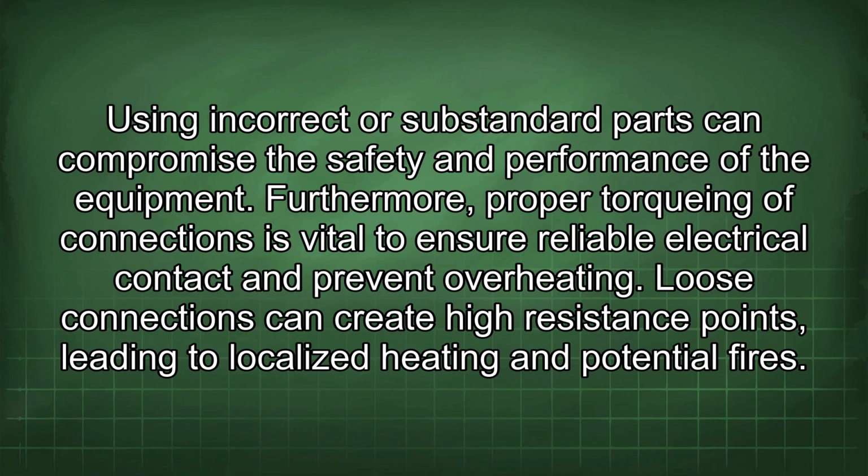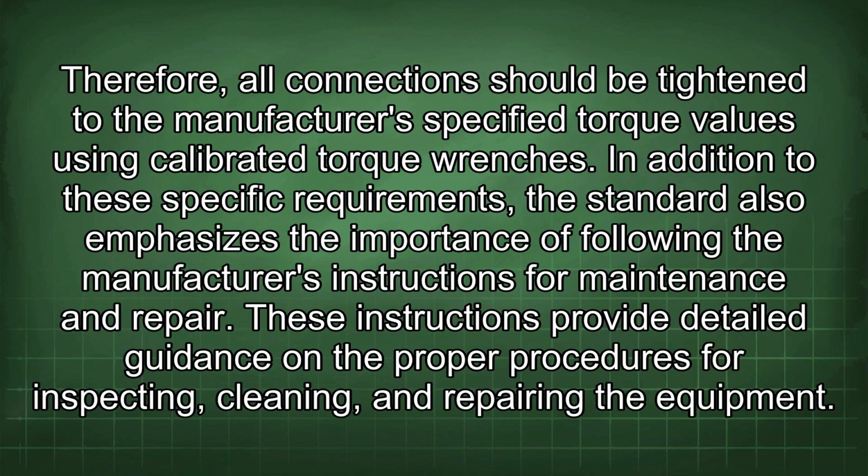Furthermore, proper torquing of connections is vital to ensure reliable electrical contact and prevent overheating. Loose connections can create high resistance points, leading to localized heating and potential fires. Therefore, all connections should be tightened to the manufacturer's specified torque values using calibrated torque wrenches.